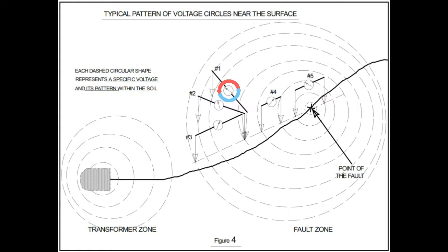Now, leaving one of the probes fixed, let's say the one in your right hand, move the other one around at approximately 45 degrees from your original reading position, and this would put you in position number 2. At this point, you should see an increase in the reading on your scale. With that, then, you would come into position number 3 and see still another increase.